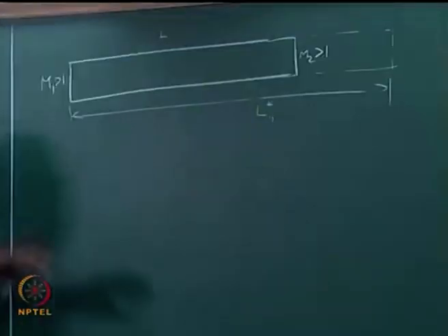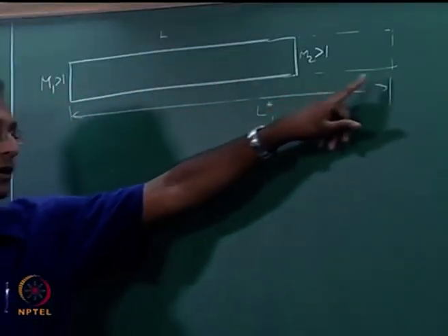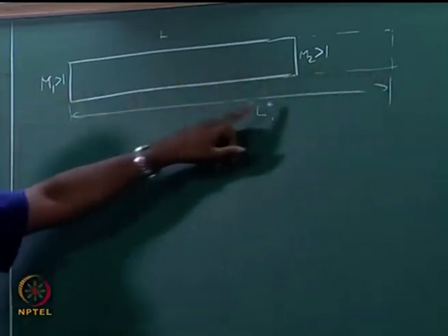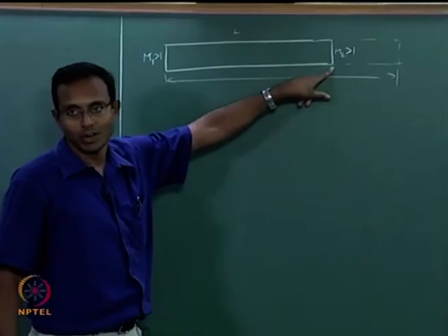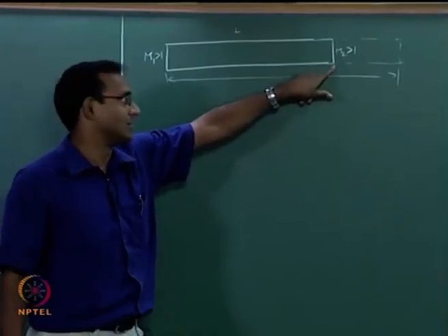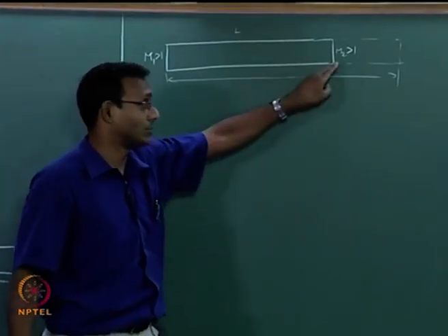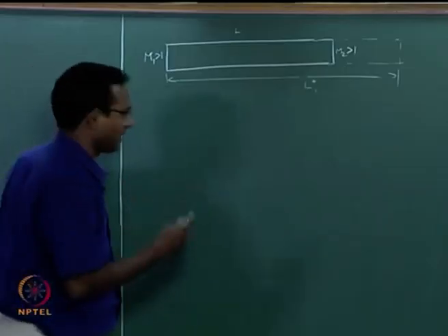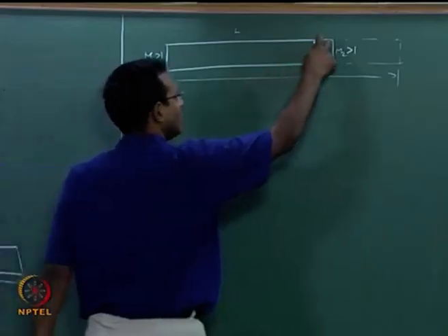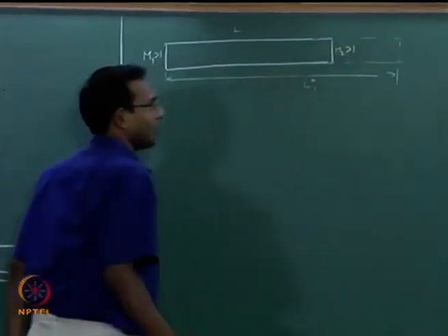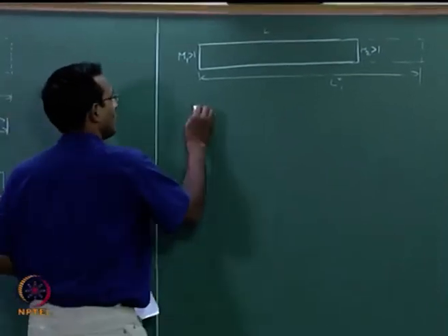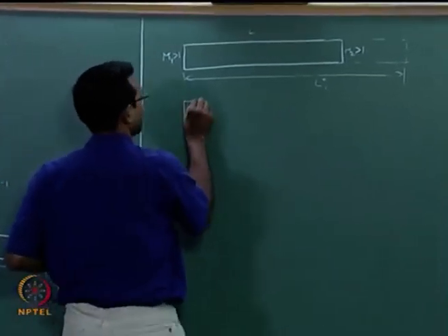Okay, it is just decreasing from M1 towards M exit equal to 1, but before that we stopped the duct. So it is not exactly equal to 1, it is slightly greater than 1. It is decreasing monotonically towards that. That is the simplest case, similar to the subsonic case. If I make this equal to L1 star, then also it is a simple case, exit will be M equal to 1. Now we will go for the more than that length case.